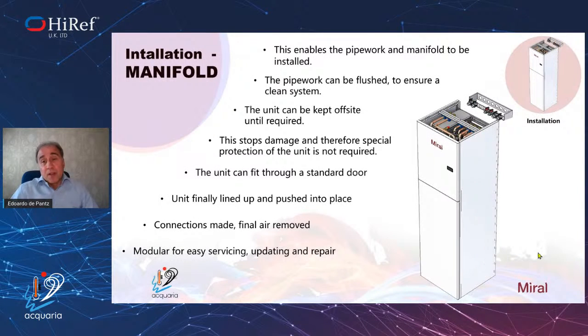That was the operation. From the installation point of view, interestingly, these units can come with a manifold as an accessory, so that when the apartment is still under construction, I can install this manifold and connect all the piping.